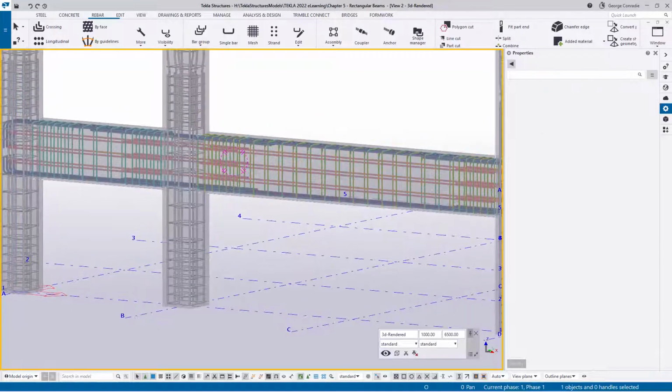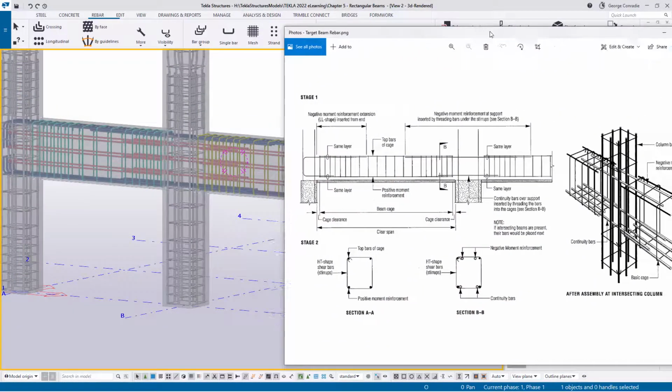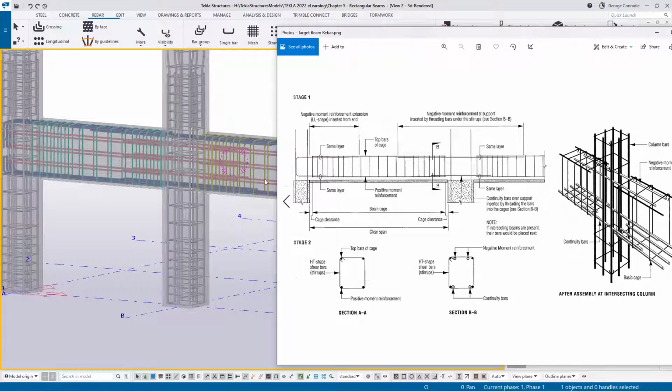So if I do that and I bring our sketch along quickly, we can see that on the end here we have our lap. Well, we didn't put a lap, but the lap will be exactly the same. Now this beam is a little bit short for that. If we lap minimum, these two laps will touch. So this will have to act as a starter bar. You see, this beam is much longer. But we've got our long lap at the top, which is same as here. We've got our shorter lap at the bottom, but still a standard lap.